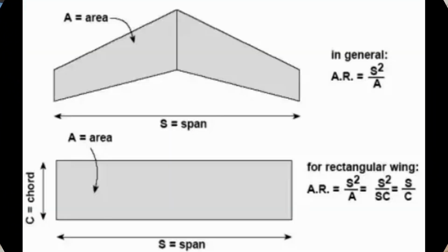So it depends upon the area of the wing, which is something you already know. Now something called aspect ratio. Aspect ratio of the wing is nothing but the length of the wing, that is the entire wing span, divided by the chord line. Chord line is from the leading edge of the wing to the trailing edge of the wing. So that is called aspect ratio. So for a given wing, the coefficient of lift is always going to be your pressure differential divided by your dynamic pressure.